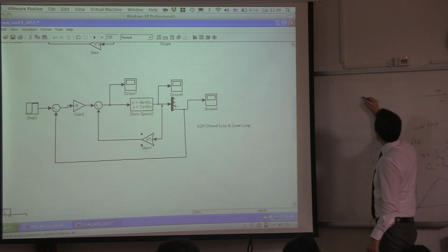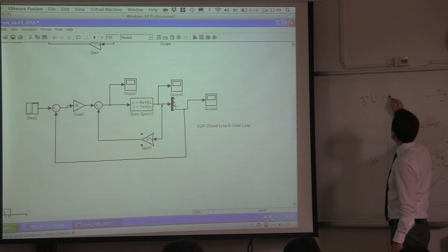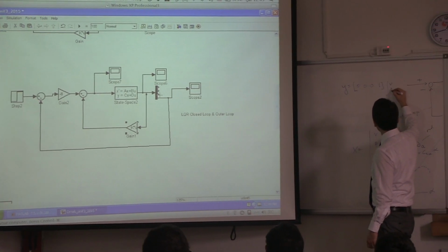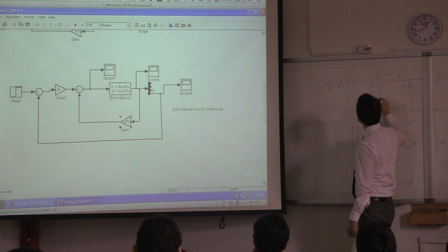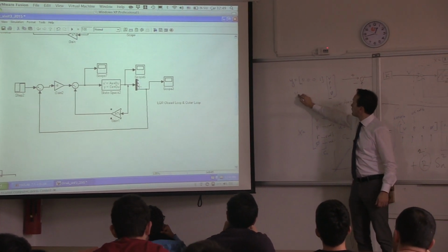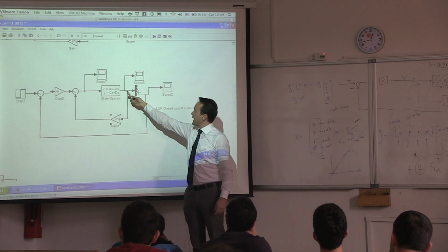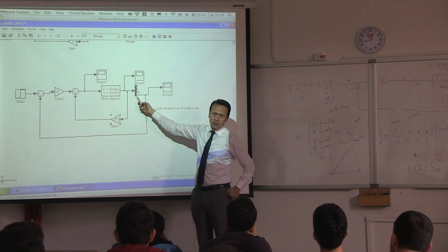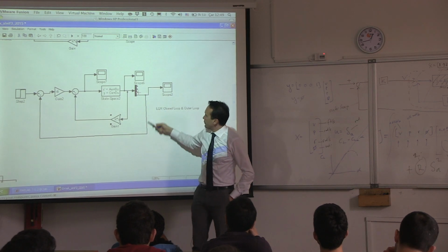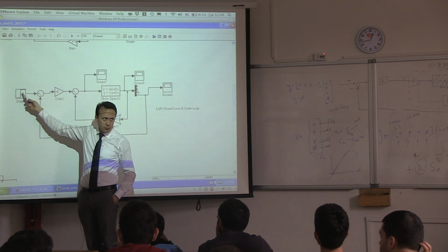So Y is equal to this, like 0, 0, 0, 1 times V, P, R, phi. So that's your C now. You multiply this with this, so Y is equal to phi. So that's what I did here, right? You take X, you take the fourth one, which is phi, and then you feed that phi back and compare it with that phi. This is now your tracking problem.